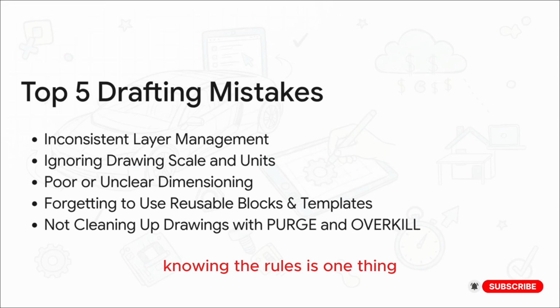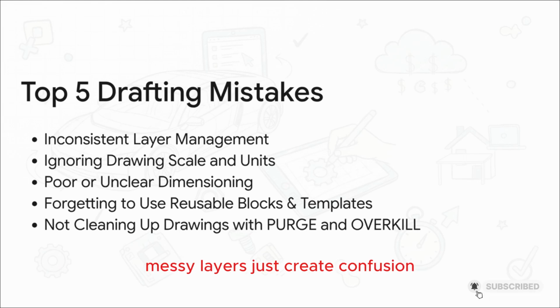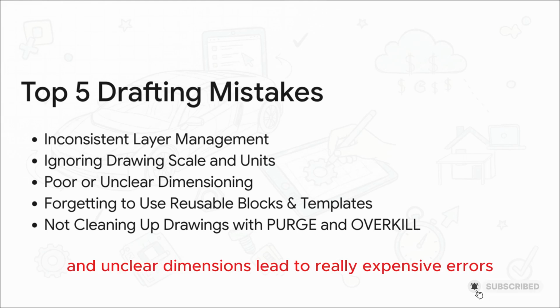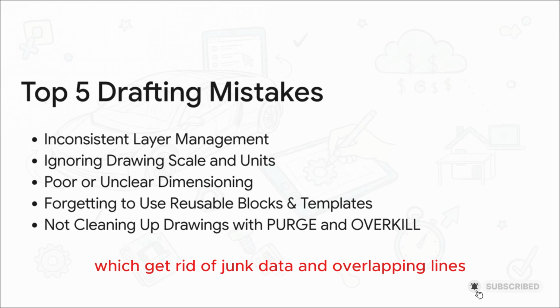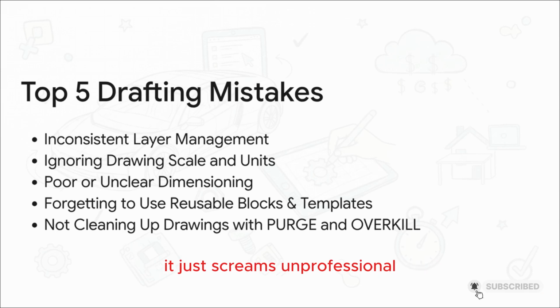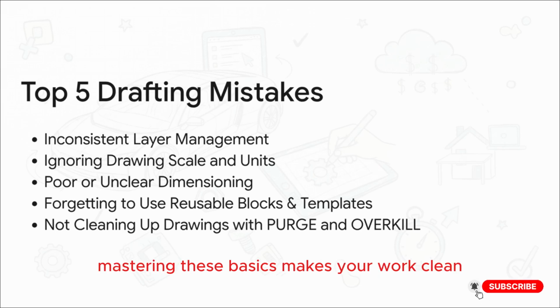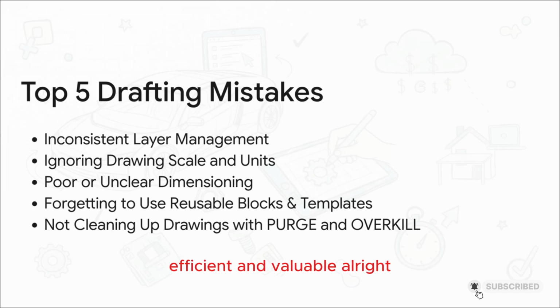Knowing the rules is one thing, but avoiding these common mistakes is what really separates the amateurs from the pros. I mean, messy layers just create confusion, and unclear dimensions lead to really expensive errors. And not cleaning up your drawings with commands like PURGE and OVERKILL, which get rid of junk data and overlapping lines, it just screams unprofessional. Mastering these basics makes your work clean, efficient, and valuable.